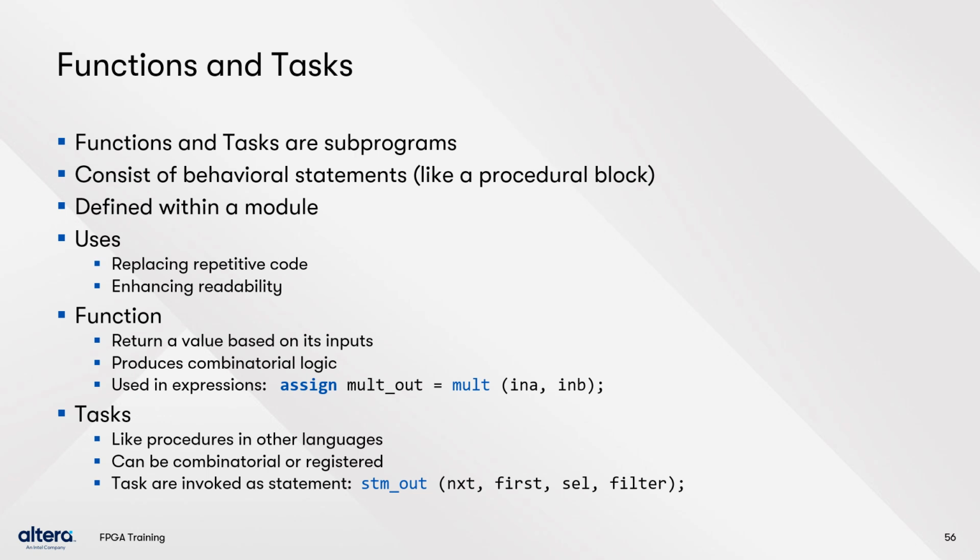Tasks can be either combinatorial or registered. A task is invoked as a statement rather than as an expression. Tasks and functions are useful for repetitive code within a module. They improve the readability of your code.